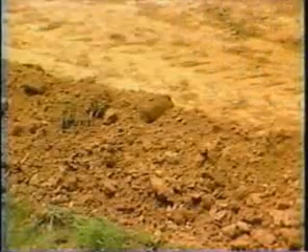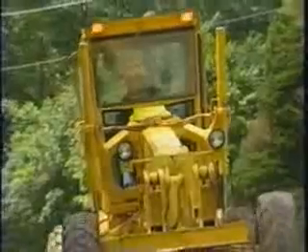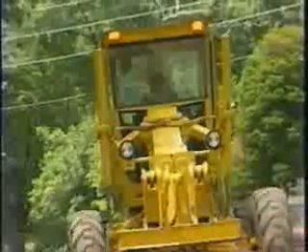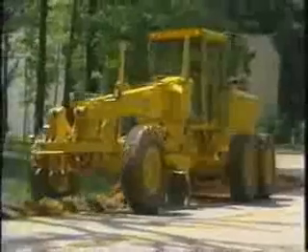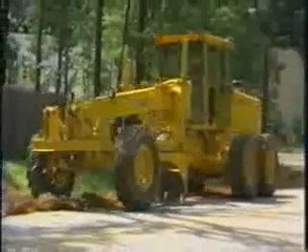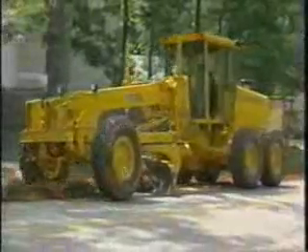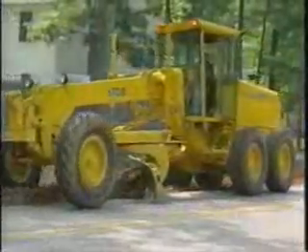If the heel is not loose, a windrow will be formed, creating a berm. This will interfere with the drainage of surface water across the shoulder into the ditch. Use a front wheel lean of 10 to 15 degrees in the direction that material is being moved. Operating speed is relatively slow, about 3 to 5 miles per hour. This prevents the blade from bouncing and creating an unevenness in the finished shoulder. The reshaped shoulder is flush with the edge of the pavement. Take care not to cut into the pavement with the edge of the blade.